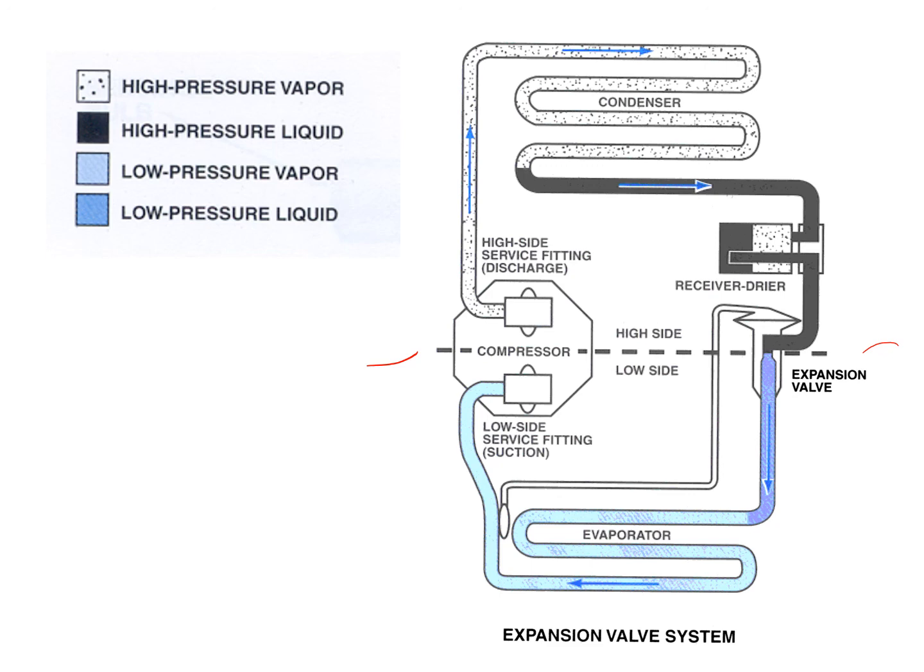And it's going to heat up and change its state from liquid, low temperature, low pressure refrigerant to vapor that's low temperature, low pressure, and flows back to the compressor. And you can see they're showing that it could be referred to as a suction. And it's just the low side sometimes is referred to as the suction side, pulling the vapor back to the compressor.